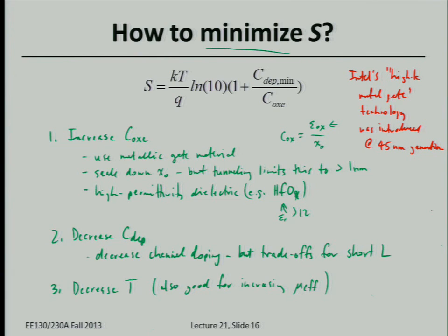Just looking at basic considerations for designing a transistor to meet performance requirements. So generally for digital circuit speed, you need to meet some minimum on-state current, and to meet a maximum power consumption requirement or limit, you want to minimize the off-state current.